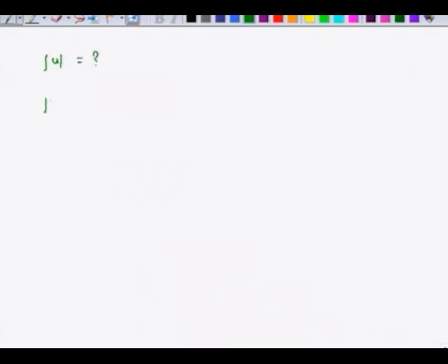Now, we know that magnitude of velocity is nothing but magnitude of pressure divided by Z, and Z is approximately equal to Z naught for large values of r. So, I can rewrite this relation as pressure magnitude divided by Z naught, and I have already found the pressure magnitude is 1.8 pascals.